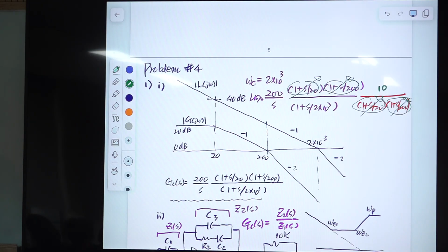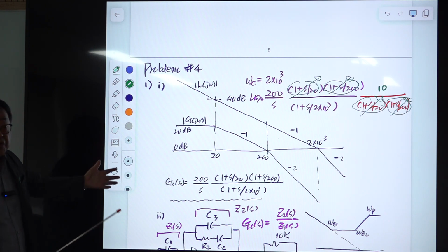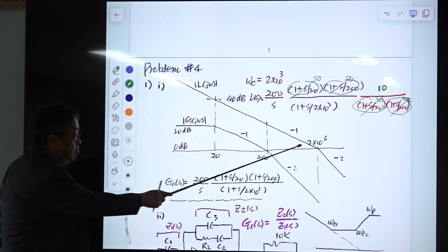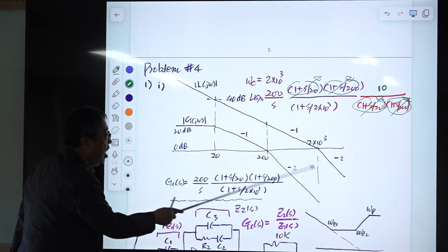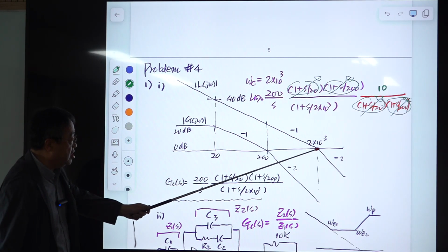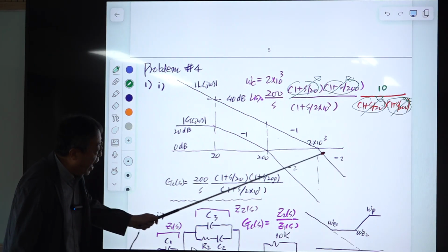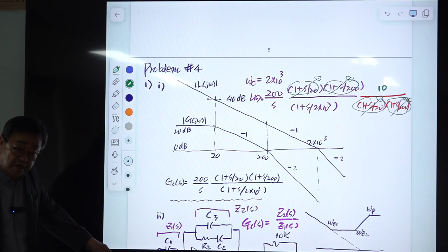then you will get the desired 45-degree phase margin. Previously, I said that you can increase the phase margin larger than 45 degrees, very large values, 90 degrees, but you are sacrificing something very much. Okay, the high frequency noise rejection characteristic is degraded. Okay, there are many others. So you put a pole somewhere at high frequencies. One good frequency is here. Maybe you want to add another one, if necessary, right?